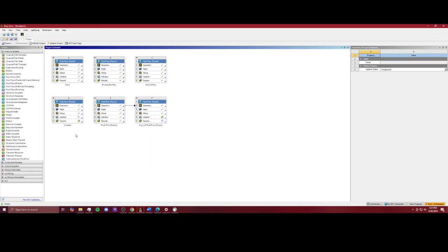So after you're done running that calculation, you're going to go ahead and do the same steps that I showed you with the Poiseuille flow, where you can analyze your results. So putting that contour on there, the vector field contour, and then analyzing the velocity profiles. So now that we're done with the Couette flow, after you're done with that calculation, you can go through the steps that I showed you with the Poiseuille flow and the post analysis. Just make that contour, go ahead and make those lines so that you can use them for the velocity profile chart. It's the exact same process.